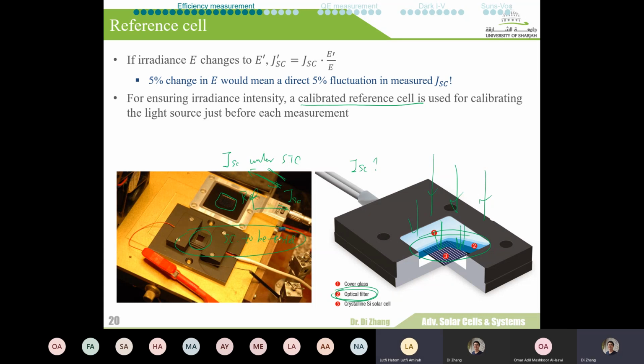This wire resistance will be represented as a drop in fill factor, right? Yeah, typically it will go directly to RS. It will be added to the series resistance. Yes, you are right. If you have a significant wire resistance, this will affect your IV characteristic, because the more RS you get, the more the shape changes. But if we do not consider the wire resistance, we cannot really tell whether the change is because of the solar cell itself or because of the measurements.